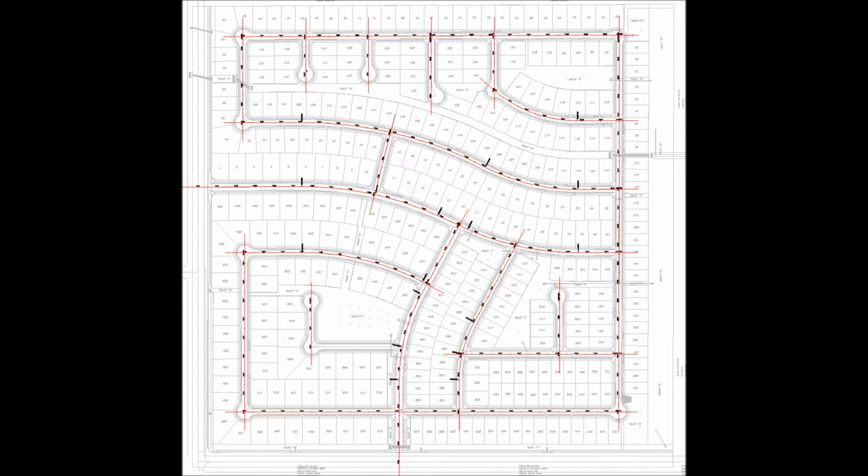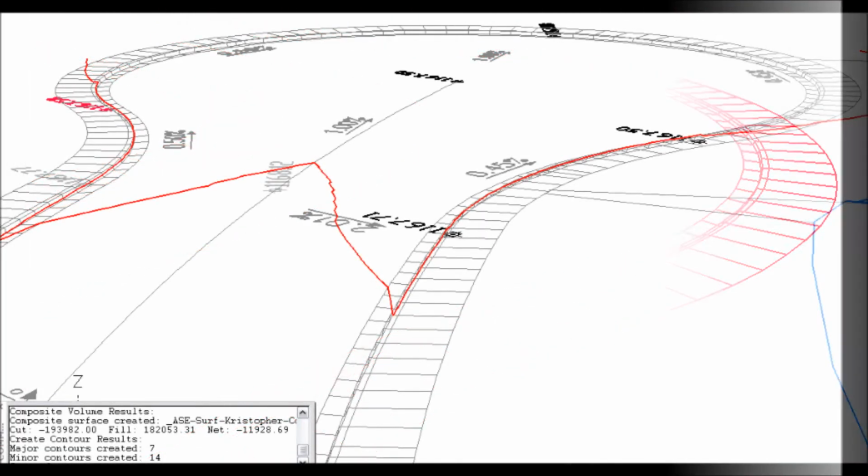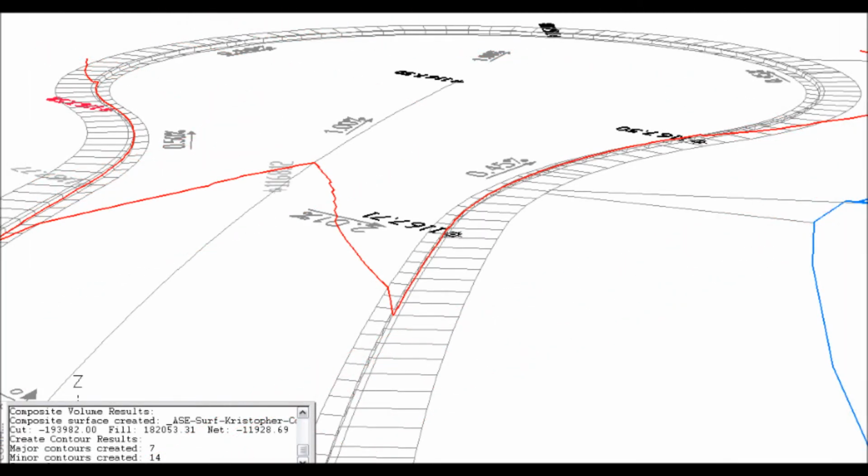One of the biggest benefits of base map control is the ability to perform detailed 3D road modeling through your subdivision corridors without the need to create any offset alignments. You can even create the same type of highly detailed geometry in the form of 3D road models through divided roads without creating any offset alignments along the face or back of curb of the islands.